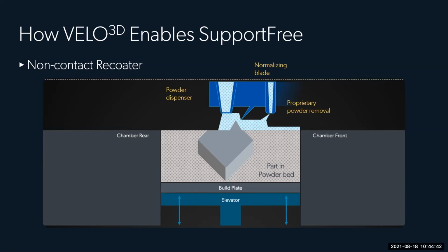There are also polymer and brush blades out there that are a little more forgiving, because instead of crashing, the blade material flexes or erodes away a bit instead of your part. But even with that, if you get a build that survives, you've got to answer the question of whether that blade material is now embedded in the material of your part instead.